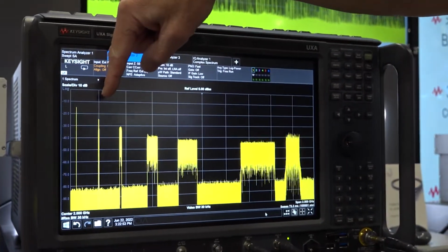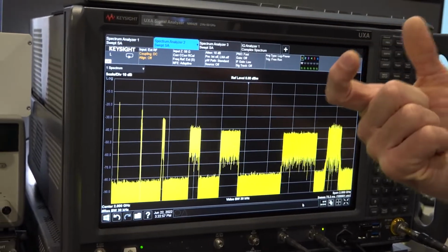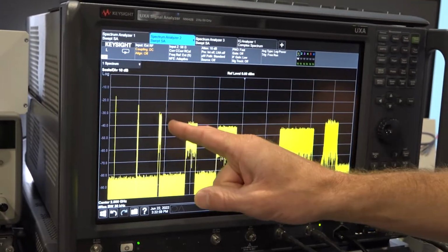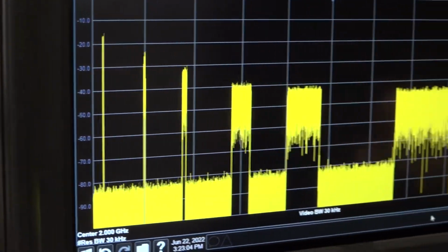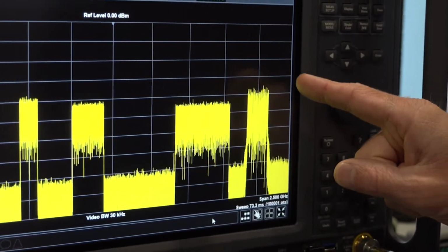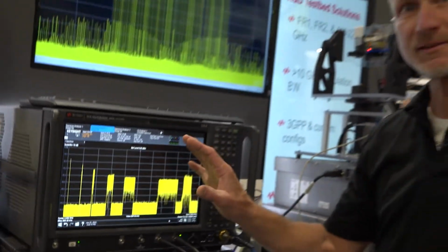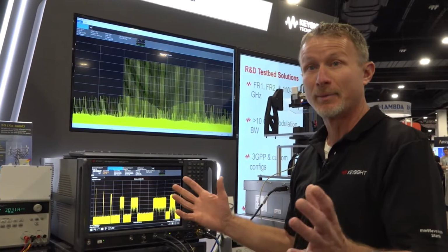This is followed by wideband CDMA, which we thought was really wide back in the day with a 5 megahertz channel spacing. Then we have 20 megahertz LTE, 100, 200, 400 megahertz new radio, and finally a 160 megahertz 802.11ac signal. Now because of the real-time processing that we're doing, we're able to do this waveform combining in real time.